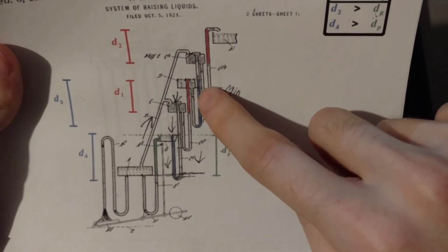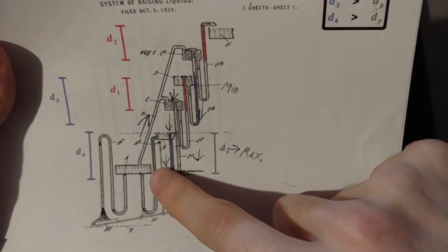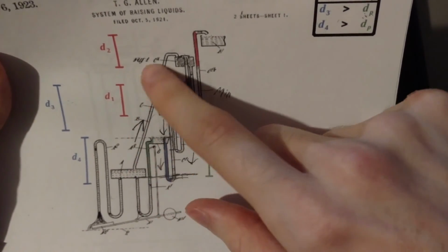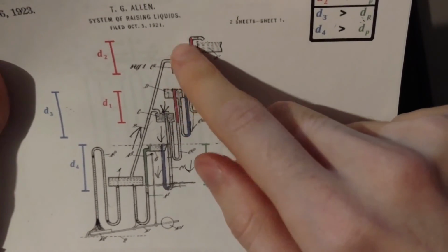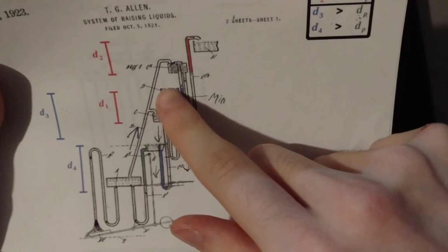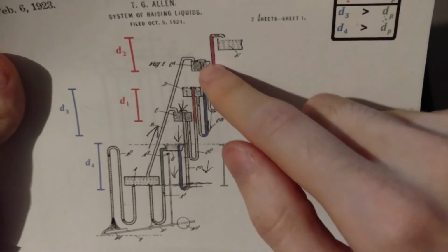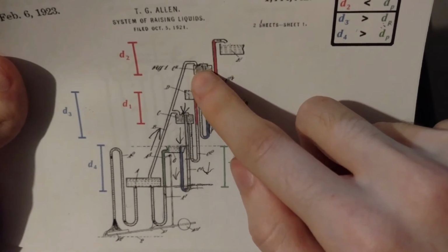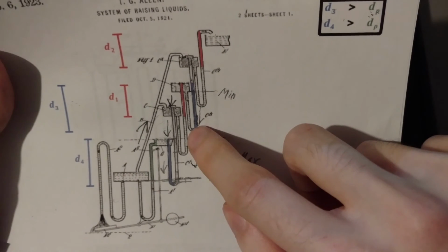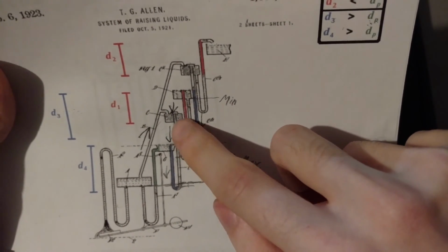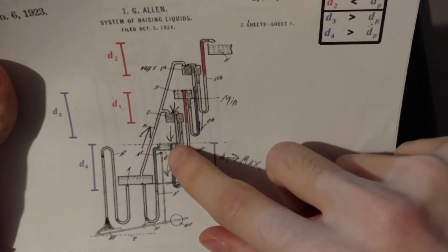So in other words, you want to have that back pressure generated here be greater than the pressure that this would have here to drive air down that tube. So you want the water pressure to be higher than the air pressure for this vessel, going this way. Otherwise the air can be pushed in that little tube there sticking up out of the top of this container, and it can be pushed down past that blue section there and bubble up into here, and that's just not going to be a good day. Same thing for this pair.